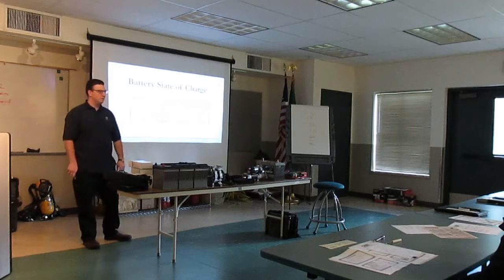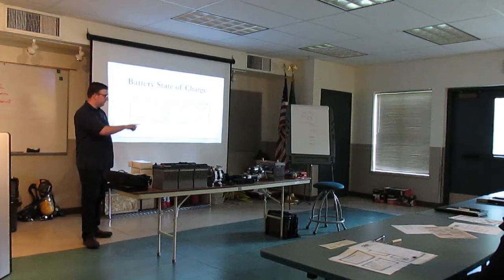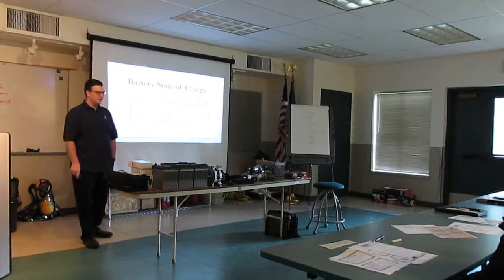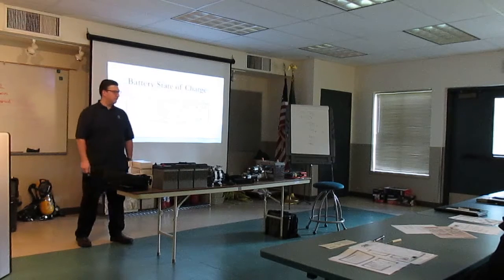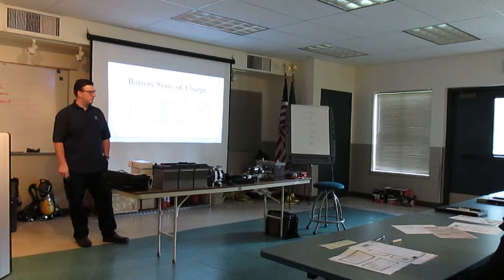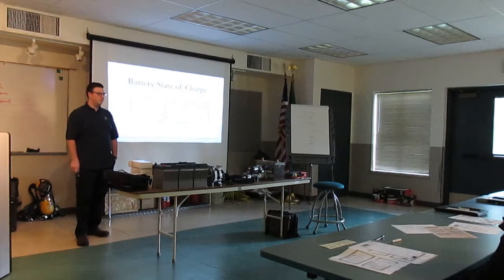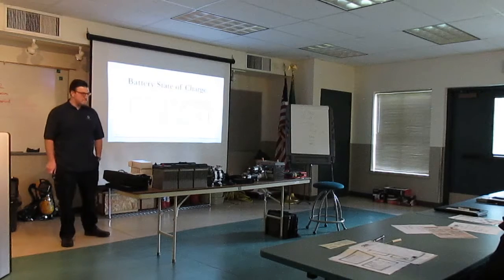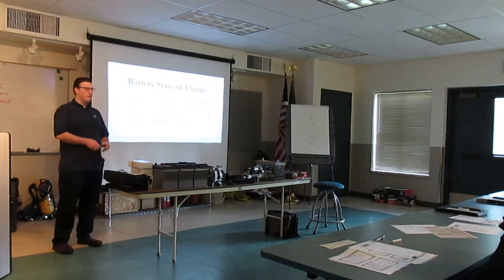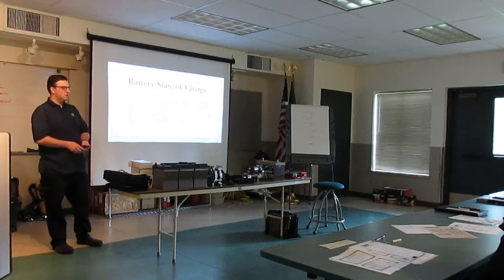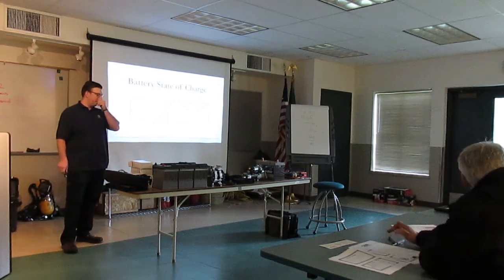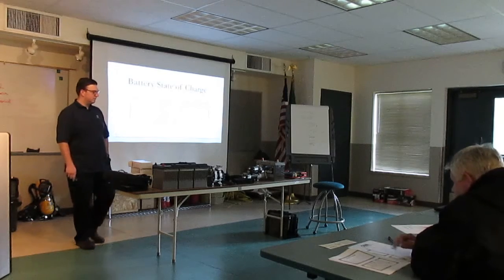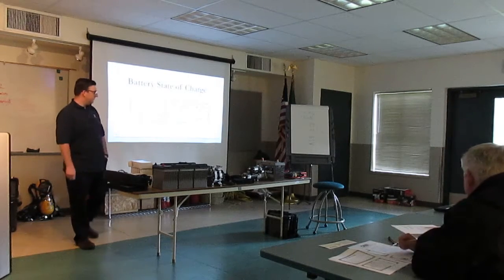So in essence, we'll get to this later on, but if you're not charging your batteries and you're at 11.9, now you're going to start your truck and go off to the call. You're expecting your alternator to charge your batteries at the call with all your scene lights on. By the way, if you're starting your truck at 11.9 volts all the time, what's that good to your starter? So think about how everything's all interdependent. So keep that 11.9 voltage number in mind. Okay, sorry, James.